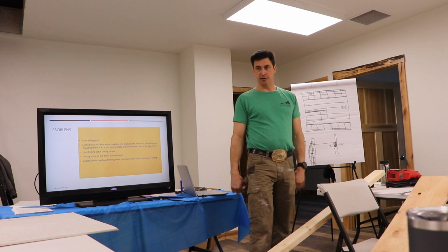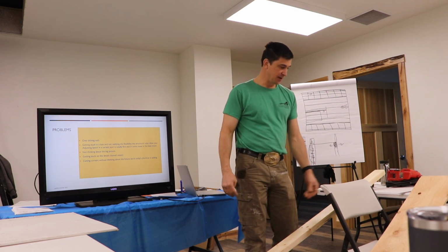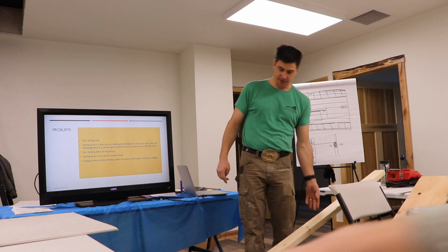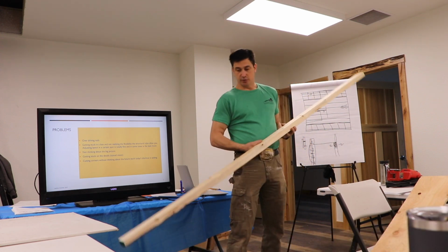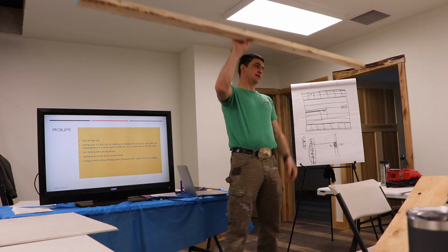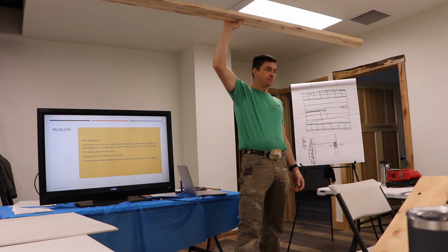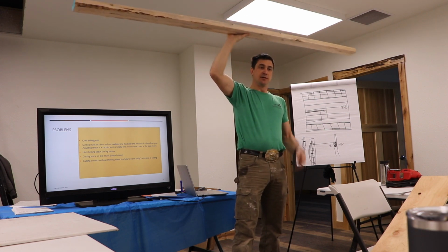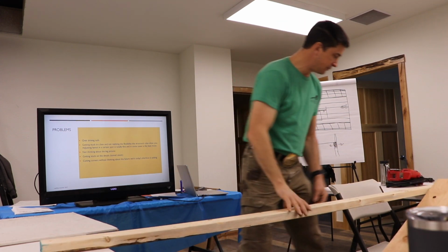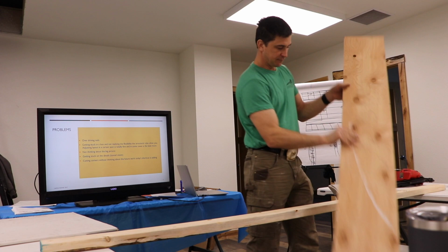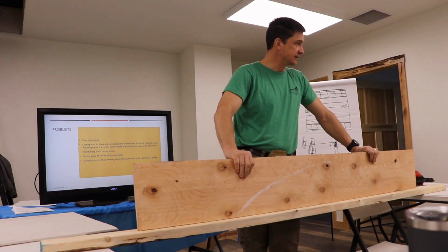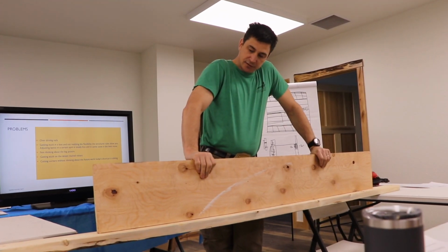guy run around and nail backer wood everywhere, and you eliminated all the cost of backer wood, and you get a better product. Particularly where I really don't like backer wood is on a top plate on a gable end wall, because most guys, if this is our top plate, your gable end truss sits on your top plate like this, and it's never tight.